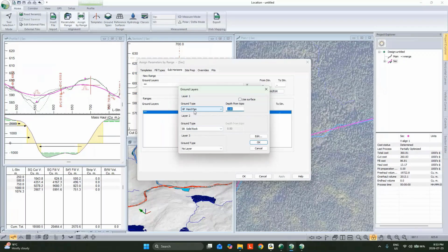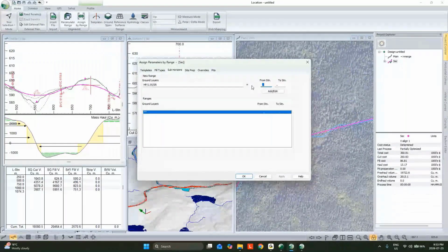If we don't, we're not stuck either. We could just use a tabular offset from the topo. So I could say I've got a meter of hardpan over solid rock, and I could say that belongs from station X to station Y. So yeah, we can track all those different geological units and how much we're cutting and filling and balancing with those for specific zones.